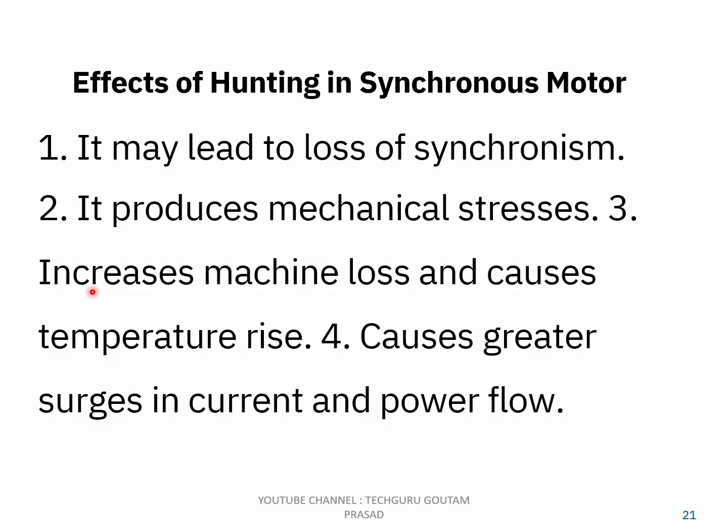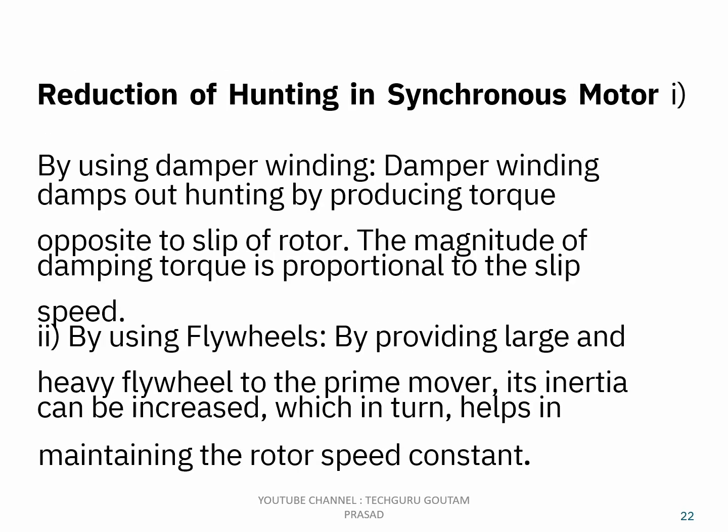Third is increase in the machine loss, which causes the temperature rise of the windings. And fourth, it causes greater surge in the current and power flow. So this is again damaging to the power system on which your synchronous motor is operating.